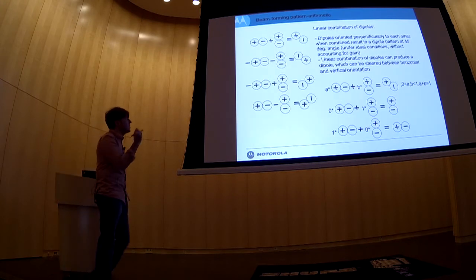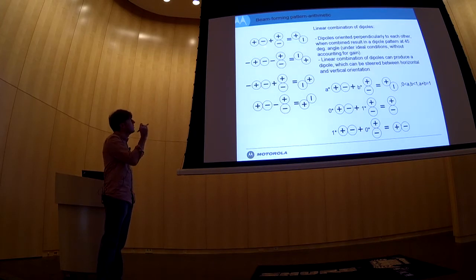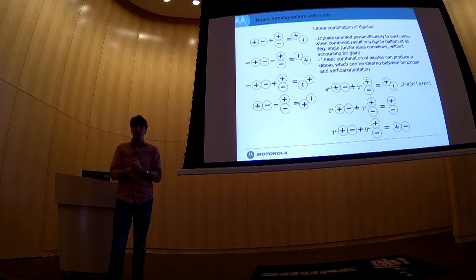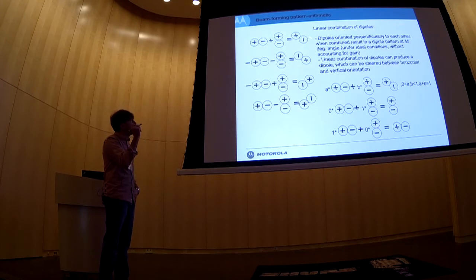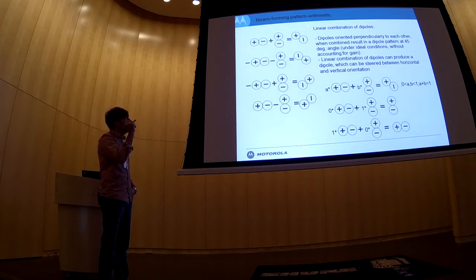An example of this is two dipoles that are obtained from two orthogonal pairs of microphones. One of the microphones could be shared theoretically. When they are added together, they can produce a dipole oriented at 45 degrees. Or in other words, the effective null will be in a different direction than that of the original two dipoles.